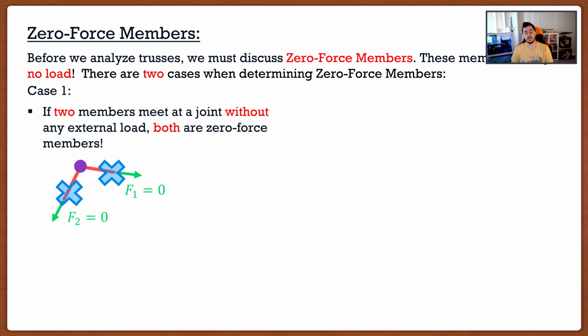The idea of equilibrium. So if I were to set my x-axis as parallel with F1 here, because you can do that. You guys can set the x-axis however you want, as long as they're perpendicular. So one thing that students always forget is that they always have it as horizontal and vertical. But if I wanted to, I can rotate it. It's completely fair game to rotate it.